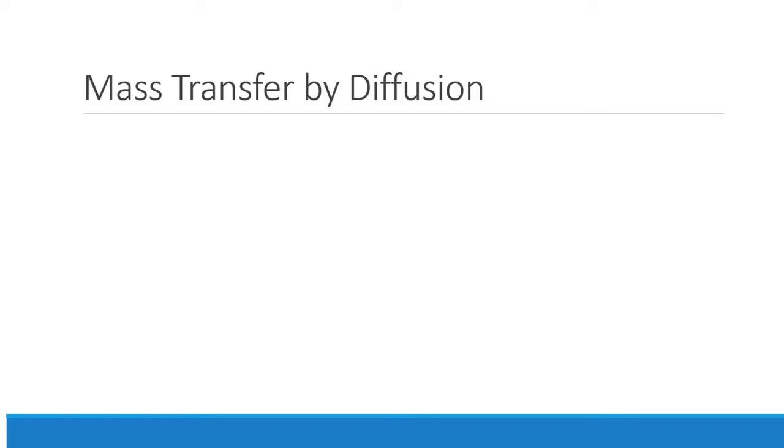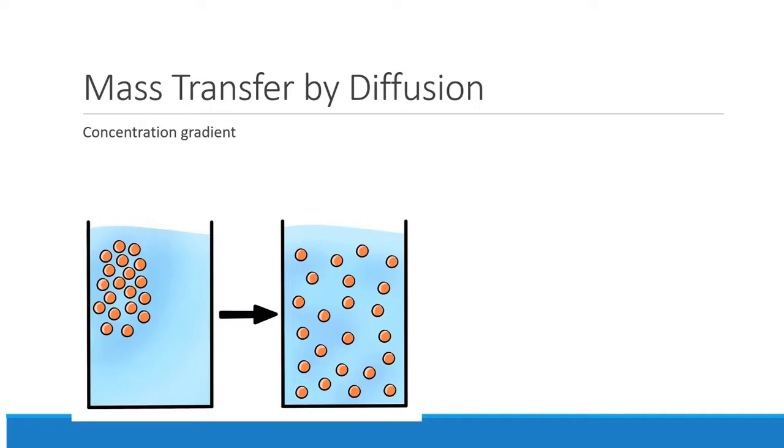In molecular diffusion, mass transfer takes place purely by concentration gradients. That is, the molecules from the higher concentration region will move to the lower concentration region and try to equilibrate the concentrations in both the regions. If the two regions are in different phases and are separated by a boundary layer, diffusion takes place through the boundary layer. If the solute in the lower concentration region is constantly depleted by consumption of microorganisms, then the concentration difference exists and the diffusion continues to take place.